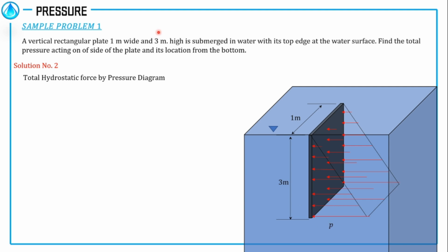at that point. To solve that, we have this equation, gamma h. Substituting, we have 9.81 times 3. Solving for the pressure will give us 29.430 kilopascals at this point. We can now solve for the volume of this pressure. From our solid geometry, the volume of this is equal to 1/2 times base, which is equal to our pressure, times height, times the width.